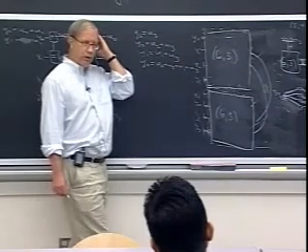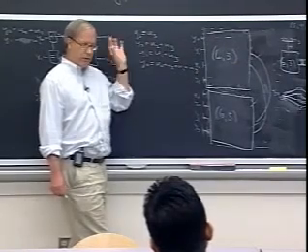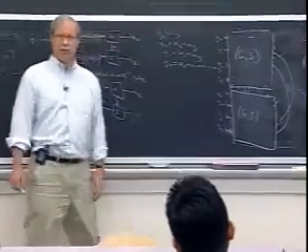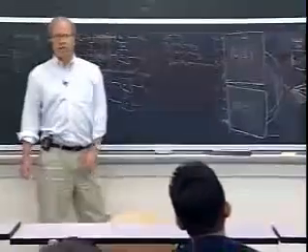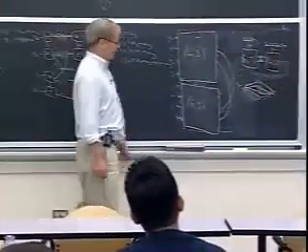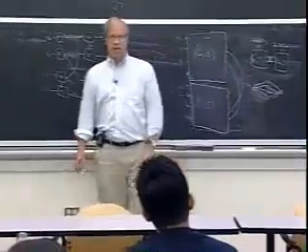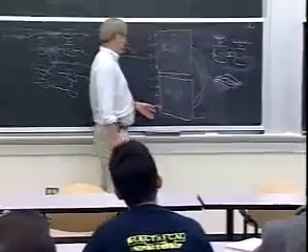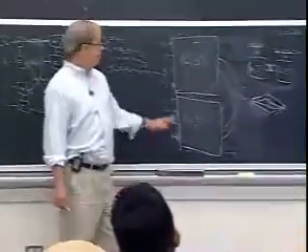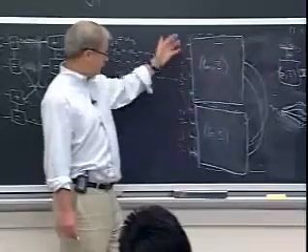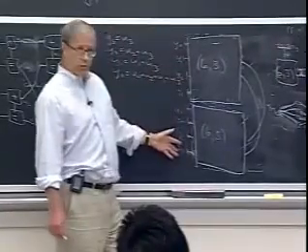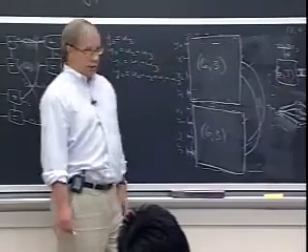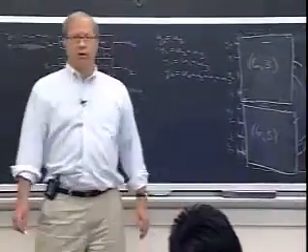Usually it is. Usually there's no difference. These algorithms tend to, at least in relatively good signal-to-noise ratio situations, both give the same answer. And the probability of bit error or word error is not markedly different, whichever one you use as a practical matter. But it's certainly possible in principle that since maximum likelihood sequence decoding gives you the lowest word error probability, maximum APP bitwise decoding has got to give you a higher word error probability.